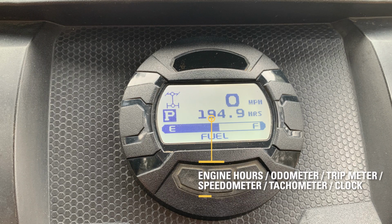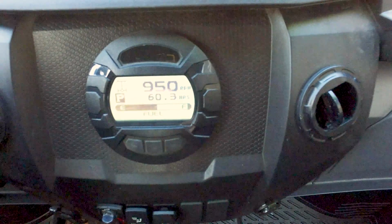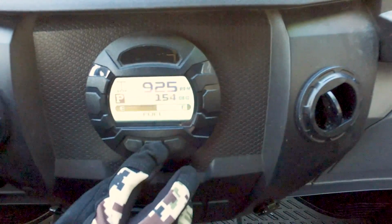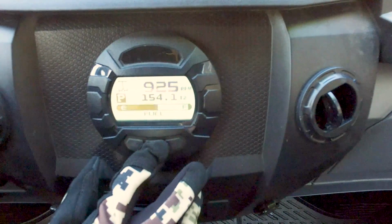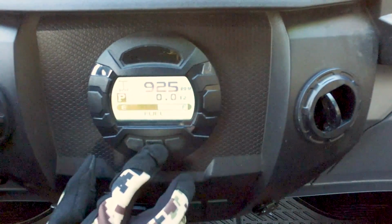This section displays the engine hours, odometer, trip meter, speedometer, tachometer, or clock. Press the middle button to choose which parameter is being displayed. The engine hour meter and odometer cannot be reset. To reset the trip meter, select it, then press and hold the middle button until the trip meter display reads 0.